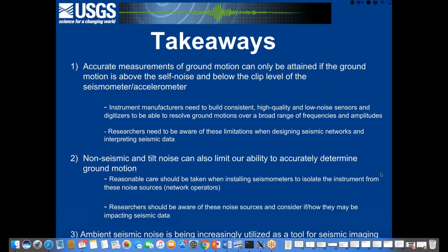This is really predominantly an effect we see at higher latitudes. But yeah, I'd say trying to thermally insulate the instrument as much as you can by going as deep as reasonably possible, and putting the sensor away from known noise sources, such as railroad tracks and trees and other objects that could likely generate signals that you don't want to record.